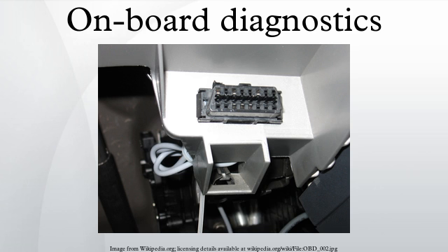Some Honda engine computers are equipped with LEDs that light up in a specific pattern to indicate the DTC. General Motors, some 1989 to 1995 Ford vehicles, and some 1989 to 1995 Toyota Lexus vehicles have a live sensor data stream available; however, many other OBDI-equipped vehicles do not. OBDI vehicles have fewer DTCs available than OBDII-equipped vehicles.